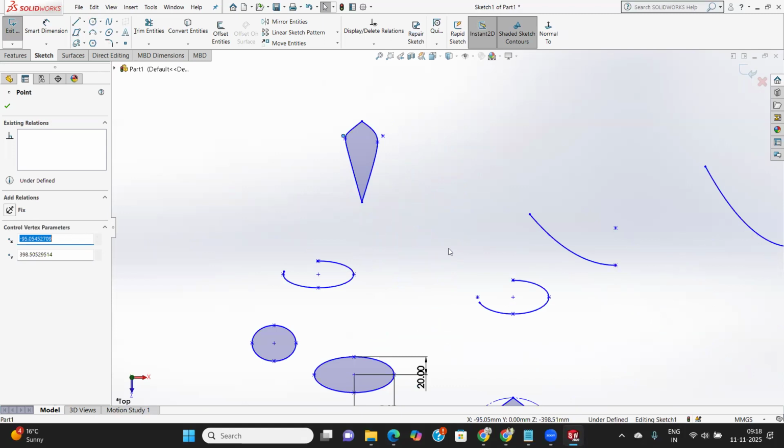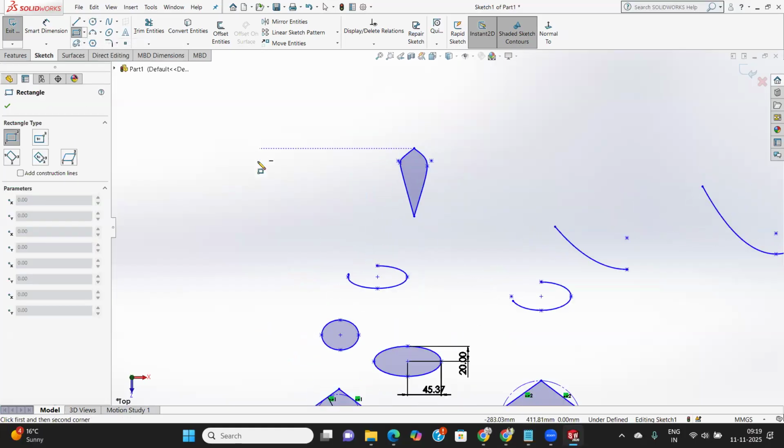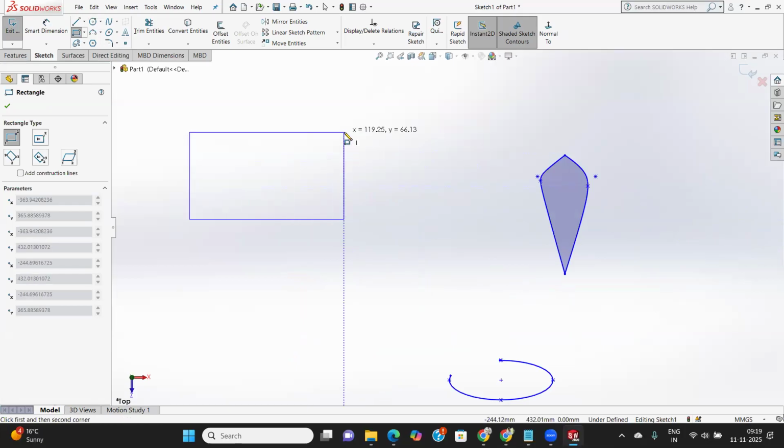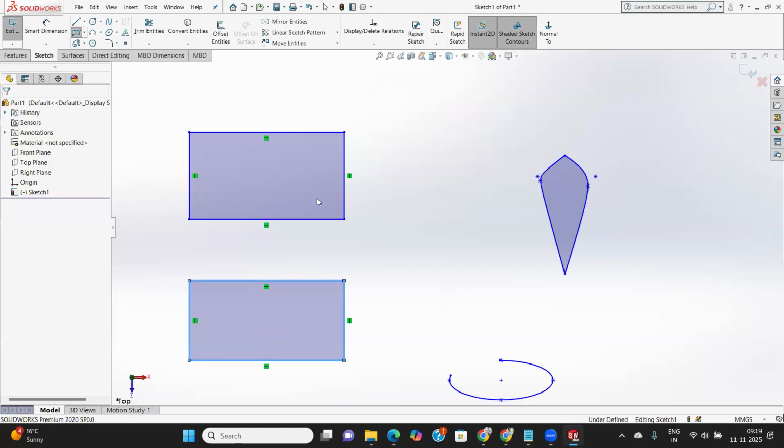Yes, clear. Then come to the next portion, which is fillet and chamfer. Do you know about the fillet and chamfer? I know chamfer. With chamfer we put different kinds of degrees, 45, 25, depending upon the tool. Fillet also, I think, is the corner radius we put to reduce the burr. Good. Both work the same way. If you want corners in a round way, then you can use a fillet. If you want corners in sharp edges, then you can use the chamfer. You can make any corners right here.